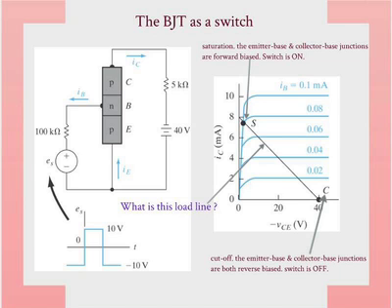If a PN junction is reverse biased, you get that current pretty much regardless of the voltage. So if you want to be very accurate, you can put that as the current in here, multiply by the resistance, subtract from the voltage, and you get that. But it'll be a very small drop, so you could probably ignore that.